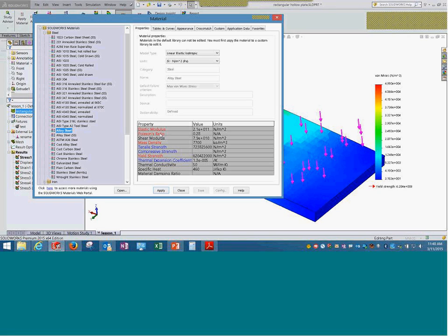Poisson's ratio is going to define a variation that is going to happen in the overall geometry. That is, if I take a certain element and compress it in a certain direction, how much planar movement is going to happen is defined using Poisson's ratio. Again, I wish I had an image to explain it. Take a local element: you may undergo a huge amount of deformation, but I would not think there would be any absolute change in volume. The volume would remain almost the same.